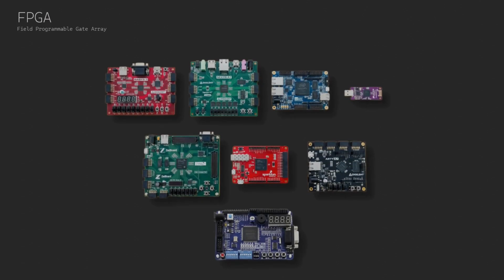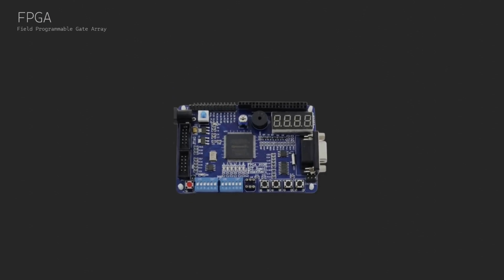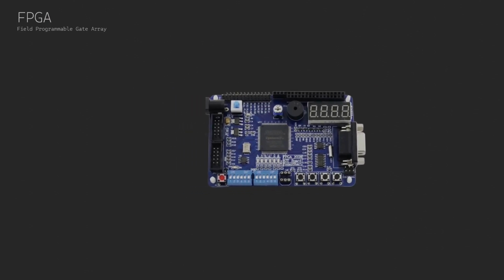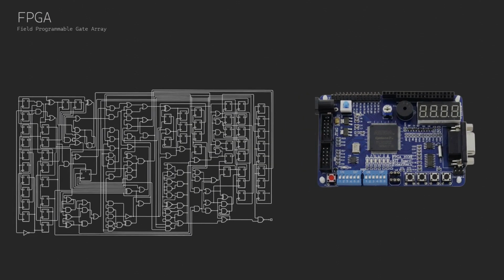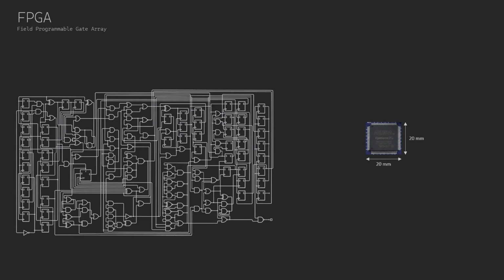You can find multiple FPGA boards from multiple FPGA chip manufacturers like Altera, Xilinx, Lattice, etc. So, where can I use an FPGA? We can use it to build complex designs where we expect quick response. On a 20mm by 20mm FPGA chip, you can have a very complex digital circuit compared to a breadboard, and you can prototype your ideas very quickly.